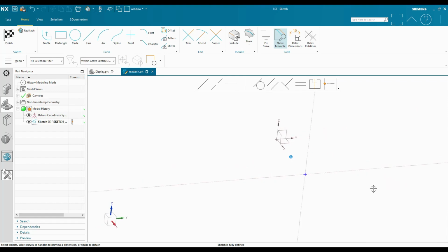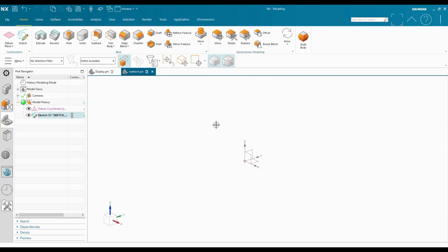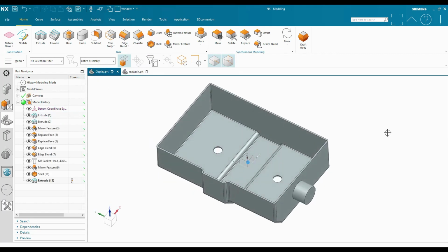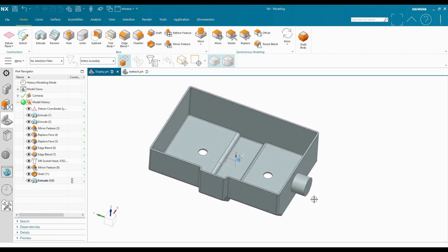If I rotate away from normal to my sketch, I can see I'm not on my origin datum plane. I'm on some new sketch plane that I've created. Reattaching a sketch even works if I have already added sketch objects to that feature. For example, in this part, I have an extruded boss that's united to this box, but let's say it's on the wrong side of my part.